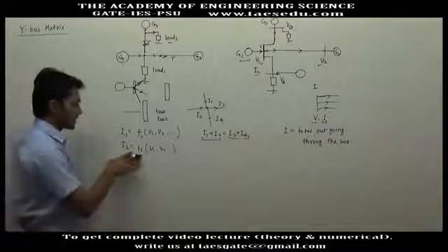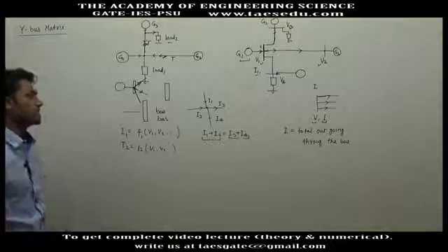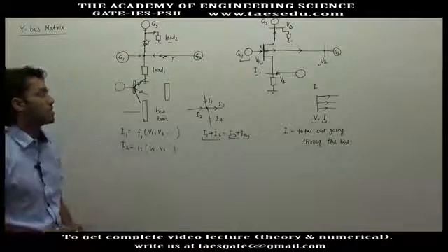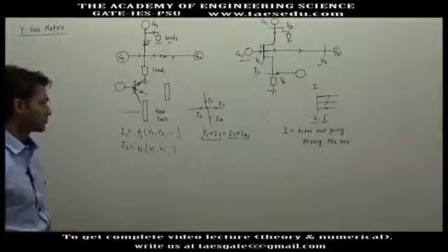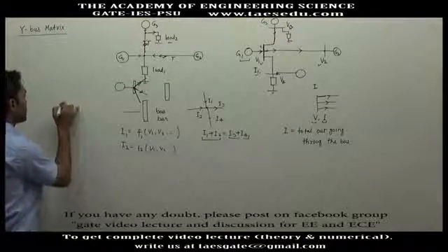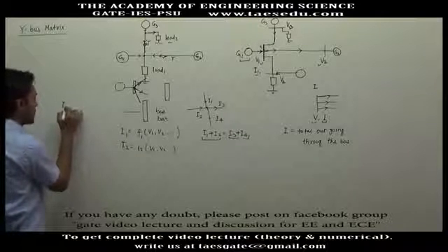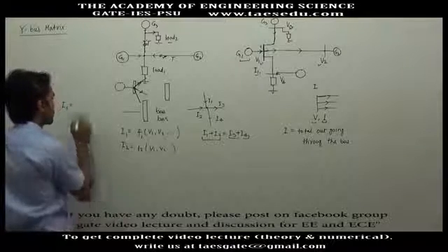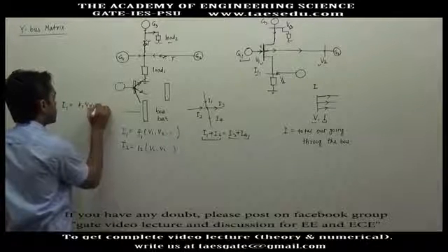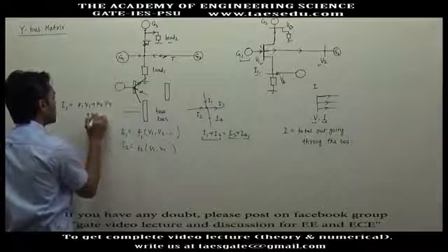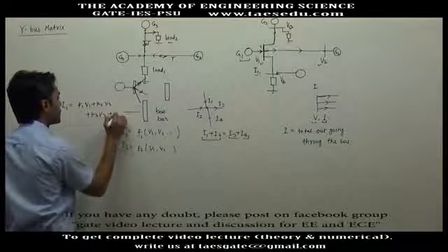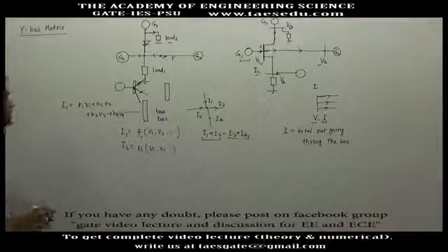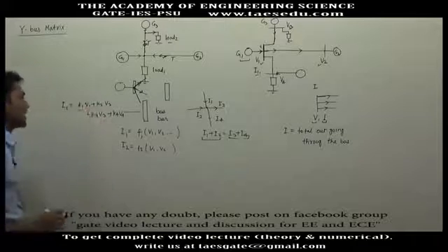And similarly we can write this type of relation for voltages. Voltage at each bus will depend on the current through all the buses. You may have an equation like I1 equals K1 V1 plus K2 V2 plus K3 V3 plus K4 V4, a linear function, and the unit of K1, K2 will be admittance.